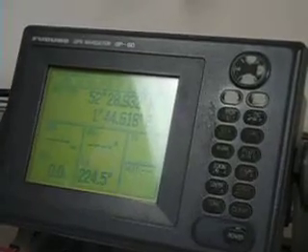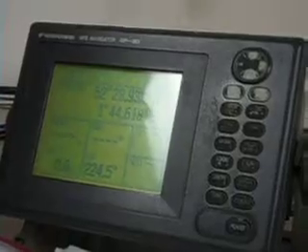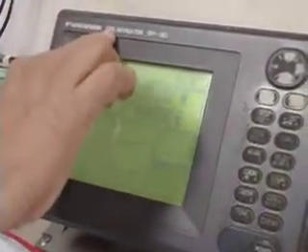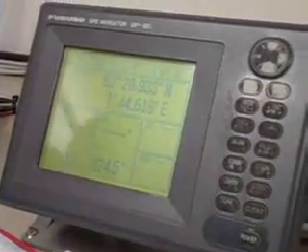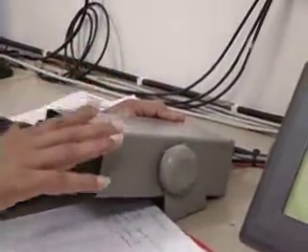Use Admiralty List of Radio Signals, input value, manually select DGPS position. Now, DGPS is differential GPS, which gives you a very accurate position. For this, your machine has to have DGPS written here, or there is an old system. There is another receiver which is written DGPS beacon receiver. This is a very old system.